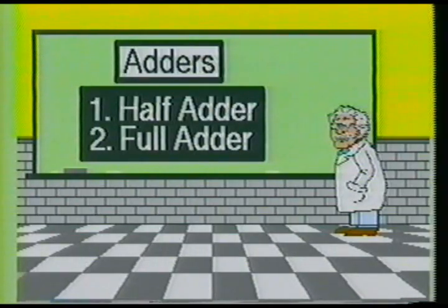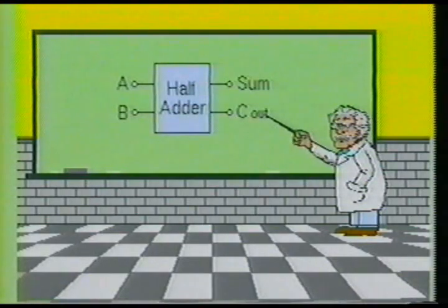You have also seen how two different types of adder circuits work, the half adder and the full adder. The basic adder stage will accept two inputs and generate two outputs. The two outputs are the sum and the carry-out. The half adder will only accept single binary bits to be added. These bits are placed on inputs A and/or B.